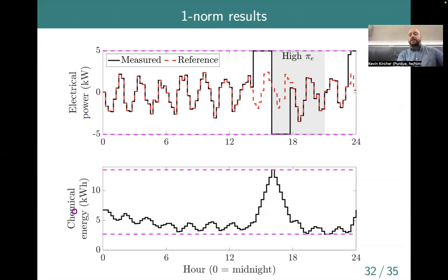Okay, so the top plot is electrical power. The bottom plot is the chemical energy that is stored in the battery. So this is basically the state of charge. This is 0 down here. So I think we don't want to go below like 20% battery. So this is whatever 20% of 13.5 kilowatt hours is. And then this is the max 13.5 up here. So you can see that we're gradually depleting the battery over time. And then we fill it all up completely before this peak period. And then we basically dump all of that energy that we just put in. And then we begin to track again. And you can see that the initial energy state of, I don't know, maybe 8 kilowatt hours is the same as the final state. So we're succeeding with that constraint that we imposed.